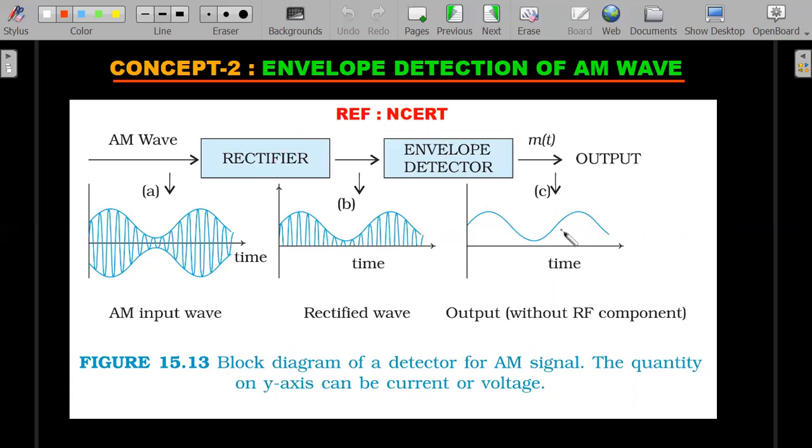Okay, so I know some of you might be thinking this message signal is not a pure sine wave, it is a slightly lifted version of the sine wave. A lifted version of a sine wave will have a DC component which can be eliminated by placing an appropriate capacitor. That is for another video. Basic understanding of this is to take care of the envelope, how to get through this envelope. Remember, this would not be a straight smooth curve because in between these two gaps the decay of this RC circuit will take place, and that is our focus in our next slide.